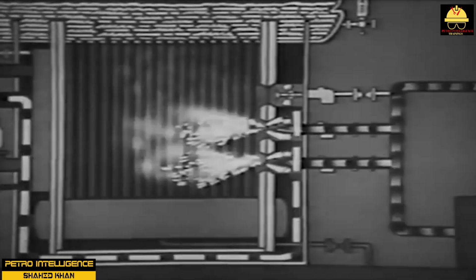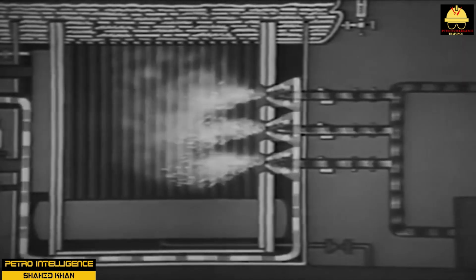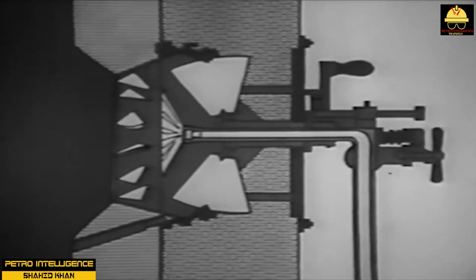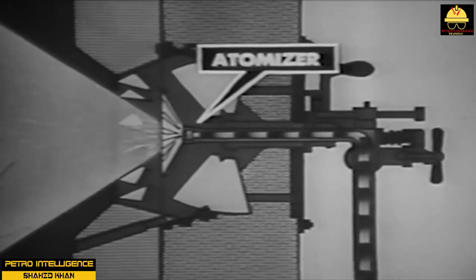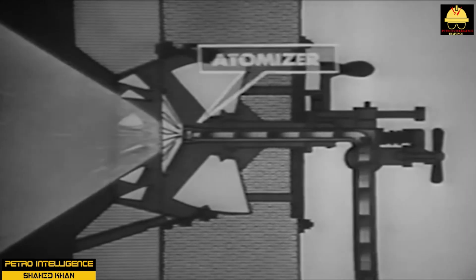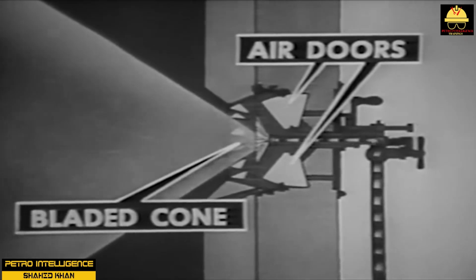Burners and air registers. Burners can be arranged on the floor or the lower walls of the firebox. There are several types of burners. Oil burners set the proportion of fuel and air and mix them by atomizing the fuel with high-pressure steam or air. Pre-mix steam atomizing burners are internal mix atomizing burners that can handle almost any fuel and are widely used by industry because of this feature. They produce short, dense flames that are unaffected by wind gusts.